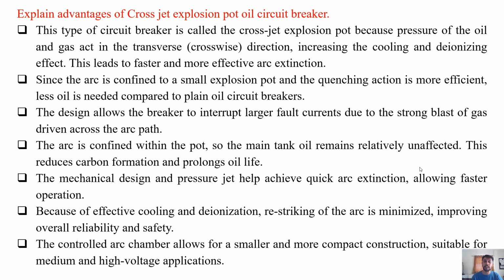Since the arc is confined to a small explosion pot and the quenching action is more efficient than the plain break oil circuit breaker, the oil required for the arc extinction is less. The design allows the breaker to interrupt larger fault currents due to the strong blast of gas driven across the arc path. The arc is confined within the pot, so the main tank oil remains relatively unaffected. This reduces carbon formation and prolongs the oil life.